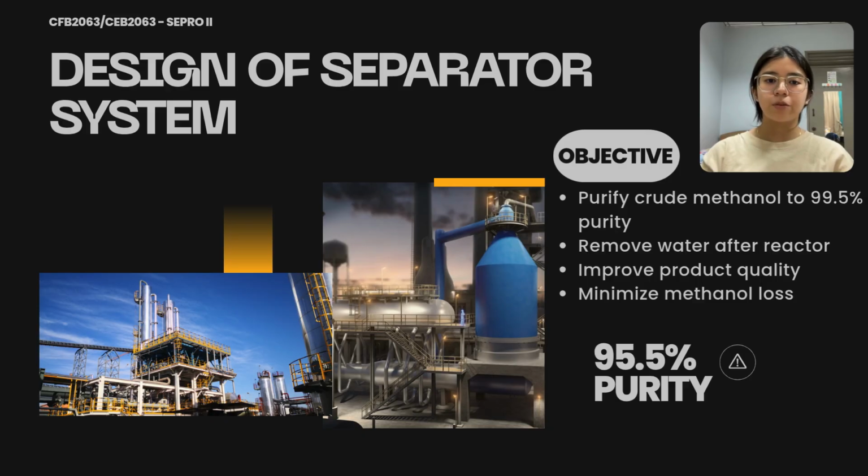My name is Ruan and I will be presenting Chapter 3, which focuses on the design of the separator system for methanol production. The main objective of this separator system is to purify crude methanol to an industrial-grade purity of 99.5%. After the reaction process, the methanol stream still contains impurities, especially water. Therefore, an adsorption-based purification system is proposed to remove the remaining water while minimizing methanol loss.